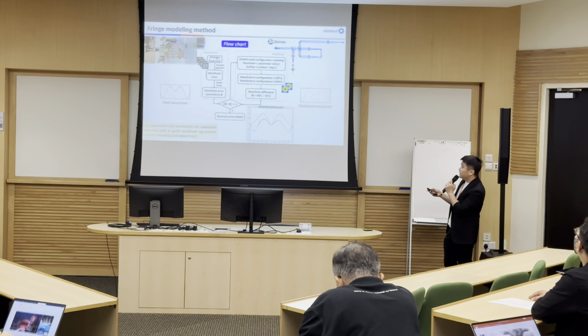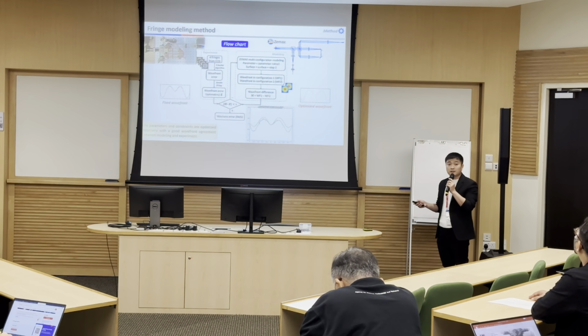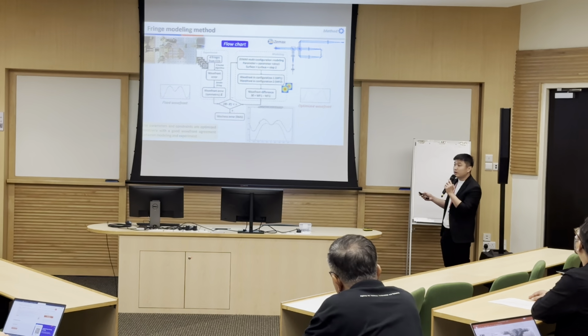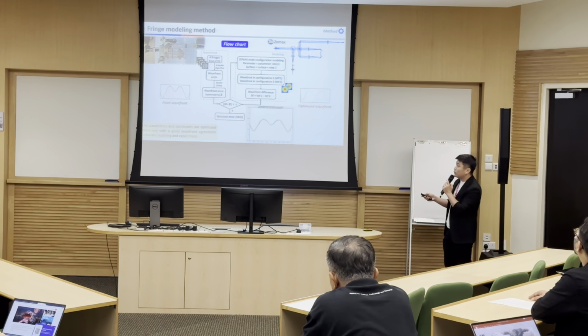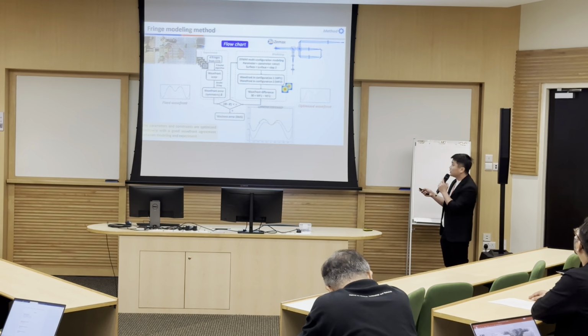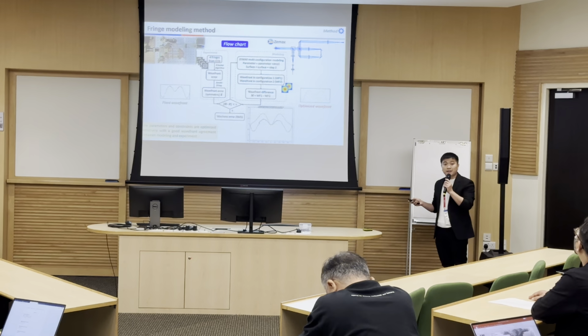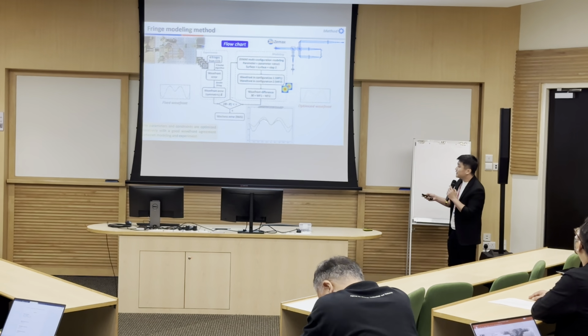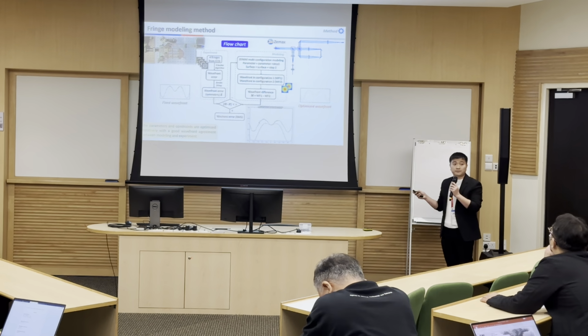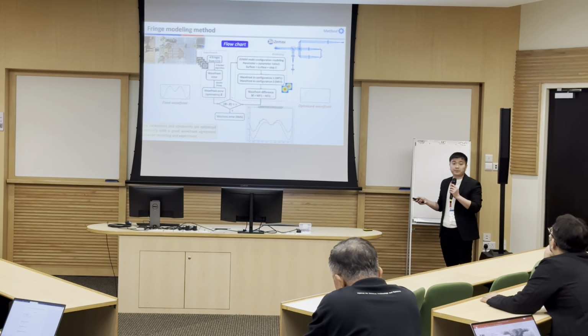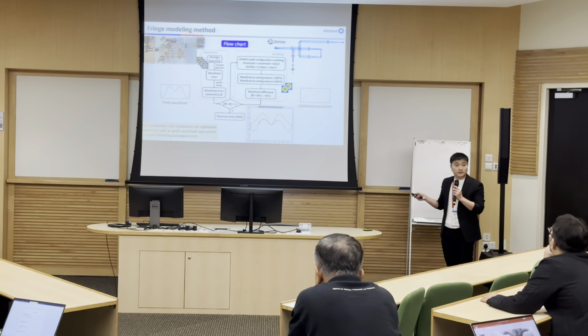In the modeling, we use two individual configurations to represent the two arms of the interferometer. By subtracting between the two wavefronts in the two configurations, we get the different wavefront. By comparing the wavefront error in the experiment and the modeling, we will get a good agreement between them. In here is the main description of my flowchart. The constraints in the modeling will be updated and optimized, so we get the good agreement by this.